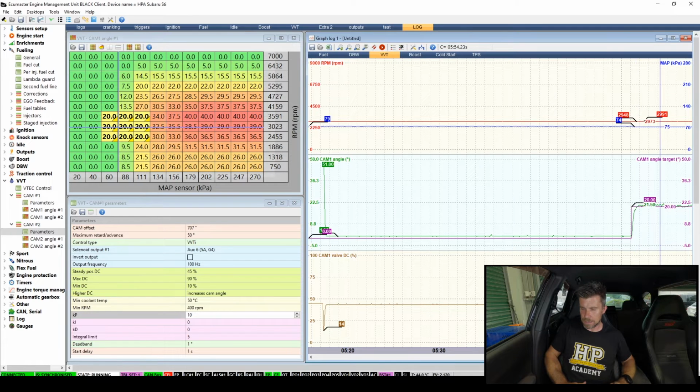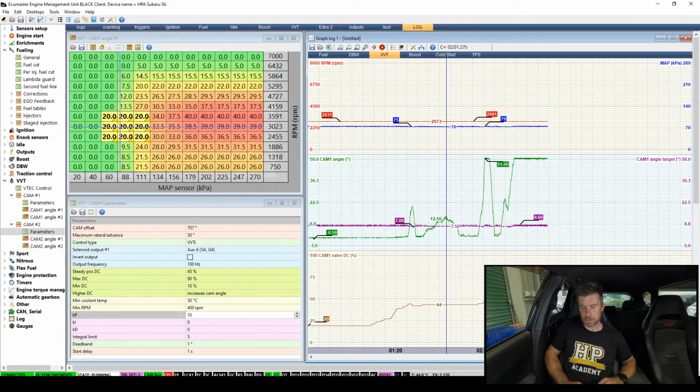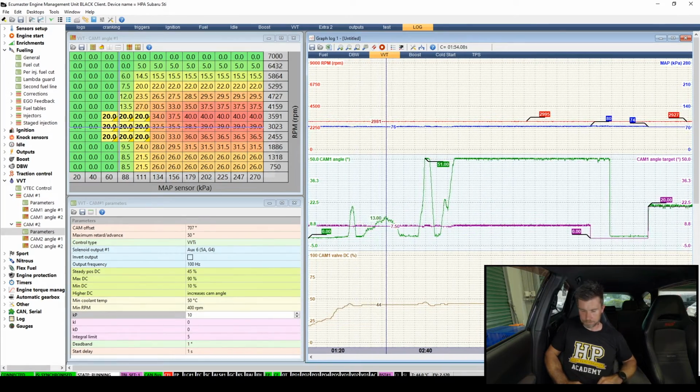You can see that the cam position has actually smoothed off a little bit. It's actually overshot as well, and it hasn't ended up right on our target. Pretty close, but that's what we can expect to see when our proportional gain isn't right. We'll get our time logger back up and running here.